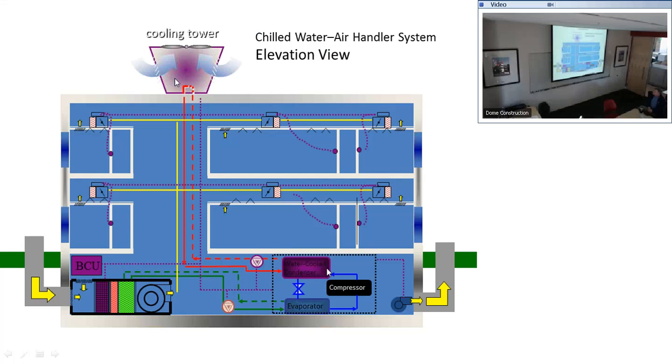So how do I reject heat? We always have to reject the heat. This chiller was creating chilled water as we need it, and we reject it through this condenser water piping. The chilled water piping was the cooling mechanism that went to the air handler. Condenser water piping, you'll hear it, is the one that goes to the cooling tower. So this is where we reject our heat for the system.